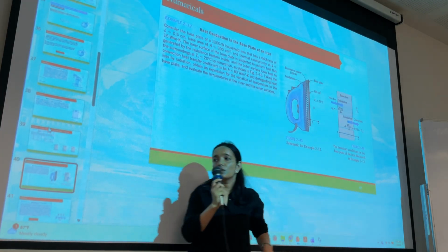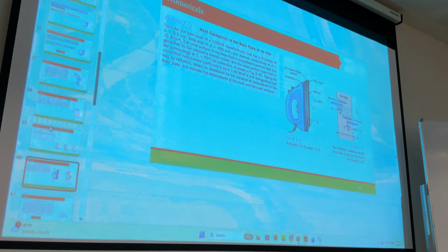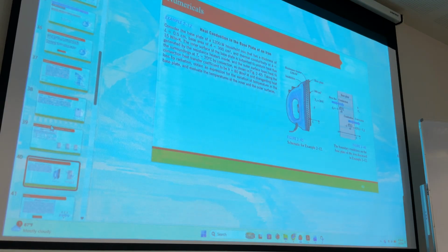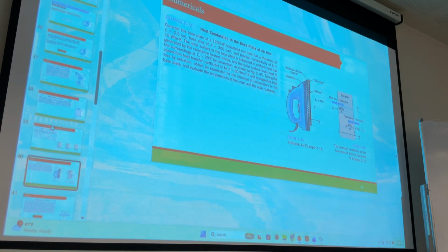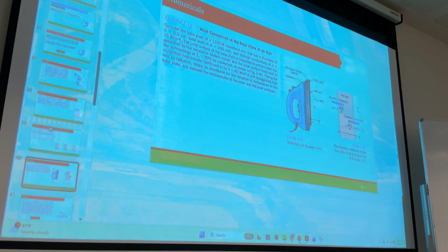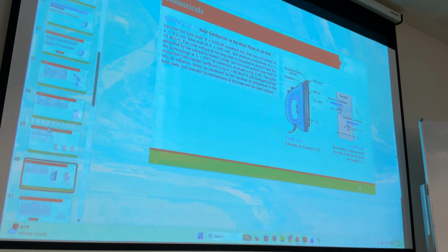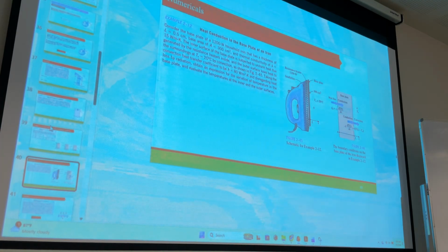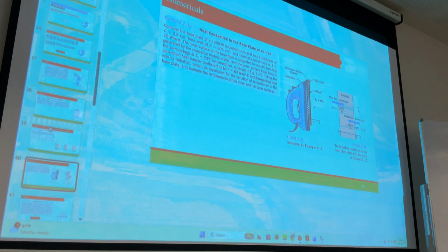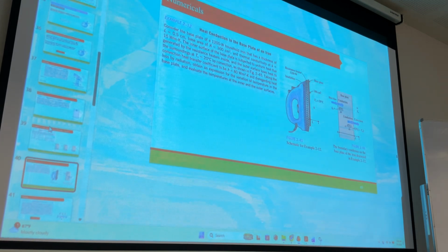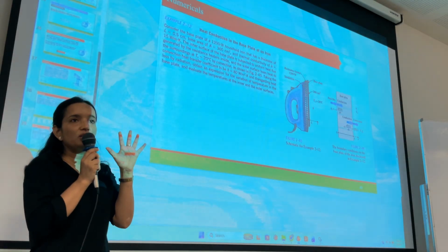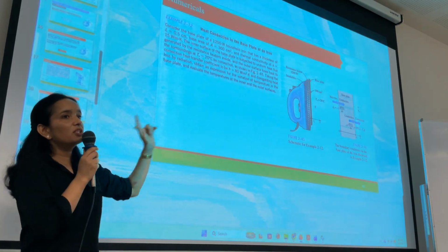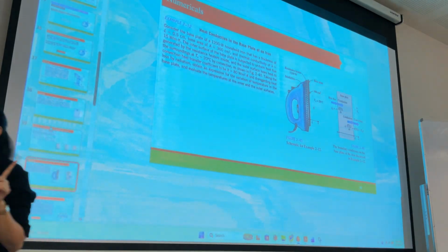So what are they asking? The convection heat transfer coefficient is given, and disregarding heat loss by radiation, there is no heat loss by radiation, only convection. Obtain an expression for the variation of temperature in the base plate and evaluate the temperature at the inner and outer surface. So first you have to identify which differential equation. You have 5 differential equations for plain wall, and the heat transfer is happening only in one direction, the x direction.